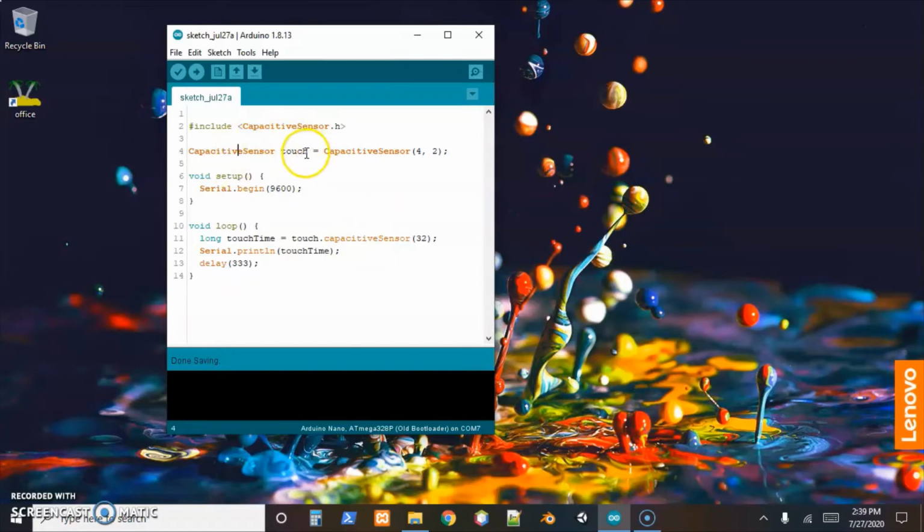So just bring in the library, creating an instance of it. And for this first part, this is something that's going to show up a lot, so I thought I'd go ahead and include it. The documentation on this is, like always with documentation, long and boring. So I got far enough to see how to initialize the object, and then get that time constant out of it. For this first pass, all we're doing is just printing out the time constant to see what sort of numbers we have, and then figure out what to do with it. Instead of reading through tons of examples and seeing what they do, I know it's returning a number representing the RC time constant, so I'm just going to see what that RC time constant is and then base my code off that.